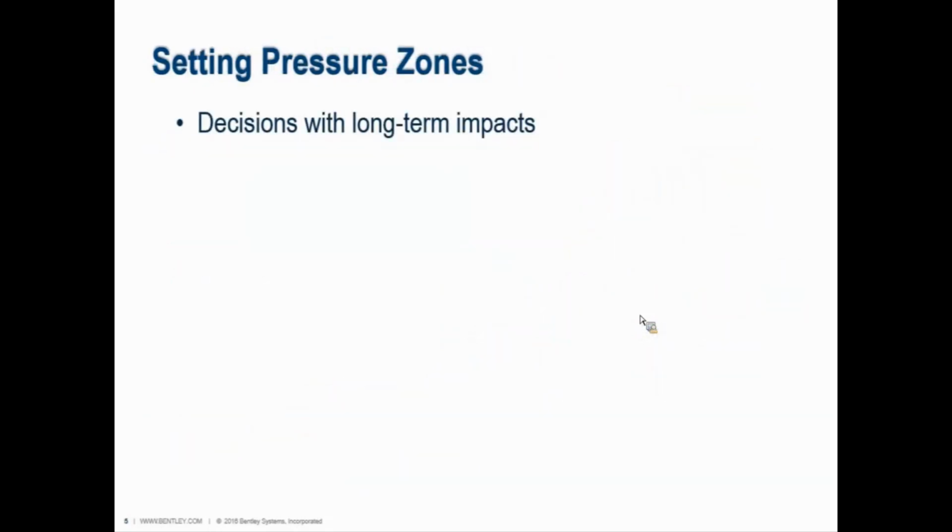When you apply some philosophy like that to pressure zones, you need to think long term, because once they're in, it's very difficult to get pressure zones out. You have people living in a certain area that you really can't have a line go right past unless you have individual PRVs to go to those individual houses, or reduce their pressure, if you have some future project that would deliver a line through there, like a high surface line or something.